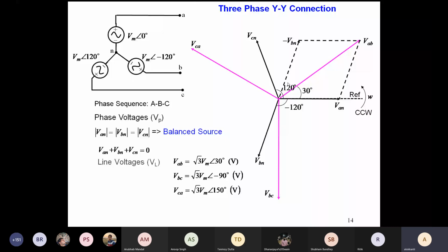So this is the generator. A three-phase generator basically consists of three individual single phases. Since this is a balanced generator, by balance we mean the magnitudes of the individual phases are all equal, but they are phase shifted by 120 degrees. Similarly, for a balanced load, we already defined earlier that the impedances are equal, and impedance equal means the real and imaginary parts are equal.